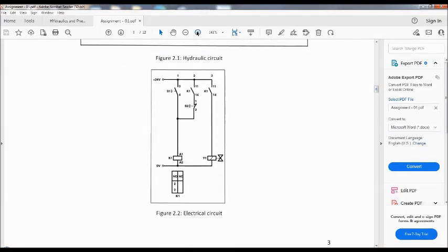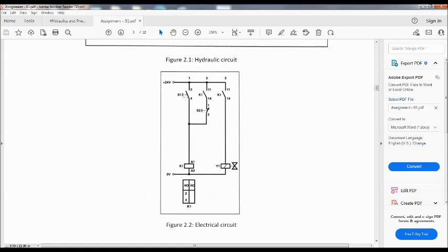The electrical circuit: there is S1 switch connected to K1 coil, and let me correct, S2 switch is normally closed, because S2 is for switching off the relay. S1 is for switching on the relay. It's like set and reset instruction. Once S1 is operated, K1 coil is continuously on. So contacts belonging to K1 coil will become closed if it is open. Since we are using both open contacts, it will be closed when relay K1 is on.